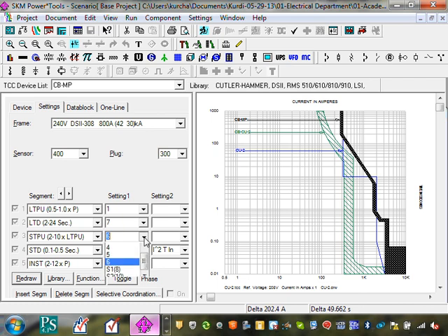Now let me go screw it up more. Let's go put it at 10. Now when you put 10, we went from 1800 amp into what? 3000 amp, allowing more current to sit in your system. Guys, all this will decide what PPE you need and what the category of the hazard is going to be. So that's an adjustable circuit breaker.